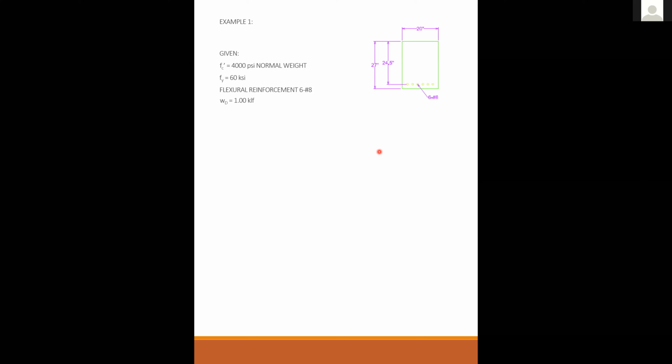Okay. Great. And really in the real world, it's kind of like that too, because how do you pour concrete? Well, you have to have formwork, and the formwork has to be shored up with posts or frames or something, right? And then you pour all that concrete in there, and then you wait for it to cure, and then you kick out the shores. And now it's feeling its own self-weight, but you got some other dead load already there.